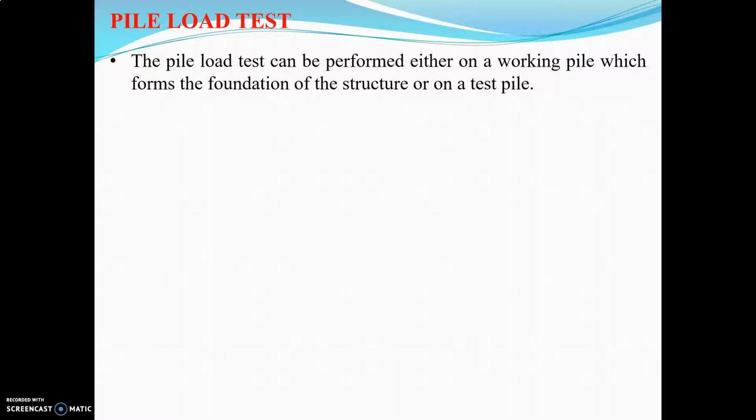Now, let us discuss the pile load test. I have spoken about static formulae and dynamic formulae. So, next one is the pile load test. The pile load test can be performed either on a working pile, which forms the foundation of the structure, or on a test pile. So it can be performed either on the working pile, on the foundation of the structure, or on a test pile.